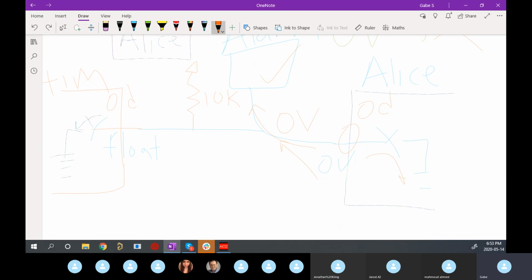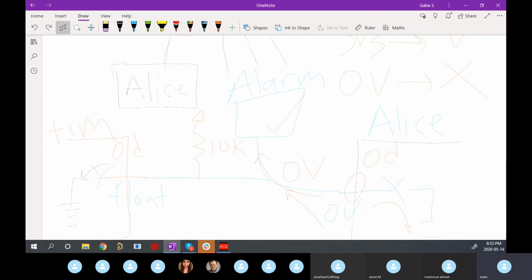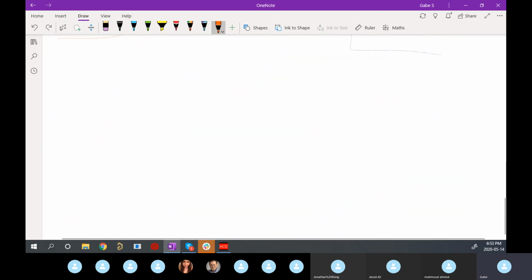And this is something we do even on the VCU. On the VCU, it's a little different in the sense that our alarm line is actually the reset line of the TMS 570. If something goes wrong outside the car, we want to be able to reset it and reboot all the code.